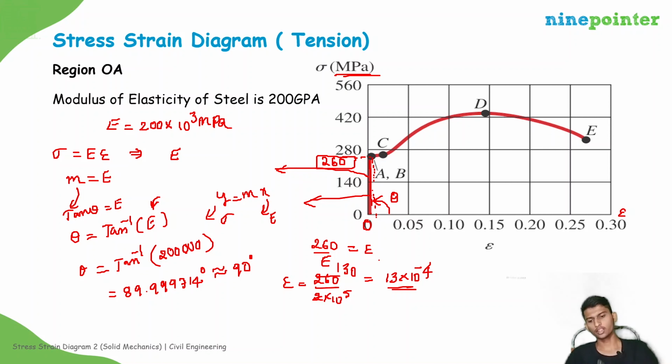Suppose it goes beyond the elastic region, then the deformations will become permanent. Suppose the beam is like this. After deformation, the beam becomes like this. Then after removal of load, the beam will look like this. Then do you feel comfortable? No. You think that it is about to fail, but actually it is not failing. But you think like that, because human psychology is like that. Because of that, we generally design these structures in the elastic region. Okay, so this is about the graph. This is a scaled graph, you can scale this.